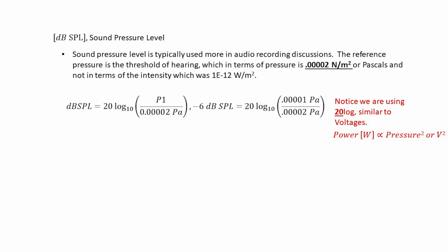But one point to notice in this is that we're back in terms of 20 log base 10 like we were in voltages. So just know that power is proportional to pressure squared or voltage squared. So whenever you're dealing with pressure or voltage, you need to be in the 20 log base 10 calculation, as opposed to when you're in power, where you're in the 10 log base 10.